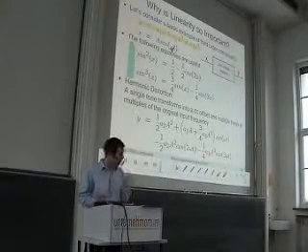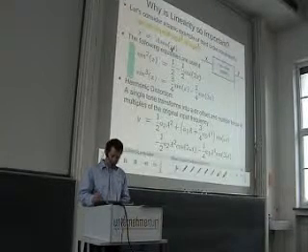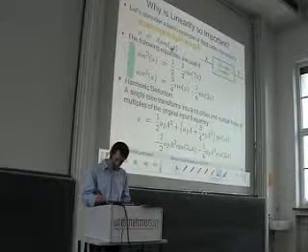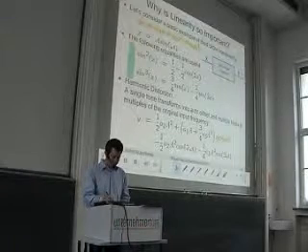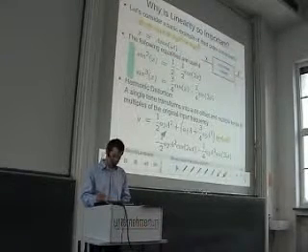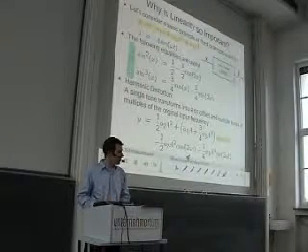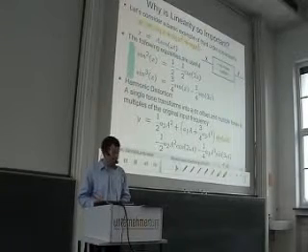Then we have seen the nonlinearity causes harmonic distortion. So at the output, we do not only get this sine signal that we expect, but we also get first a DC component, then a harmonic component at twice the frequency, and a harmonic component at 3 times the frequency.